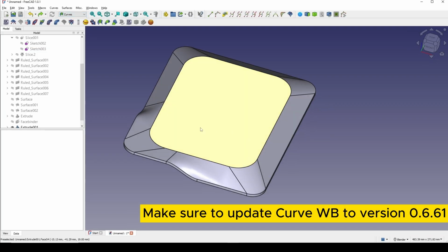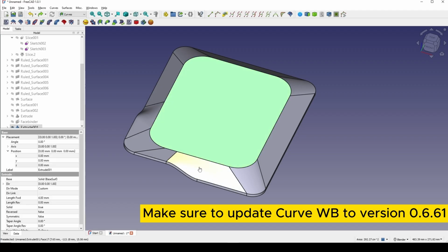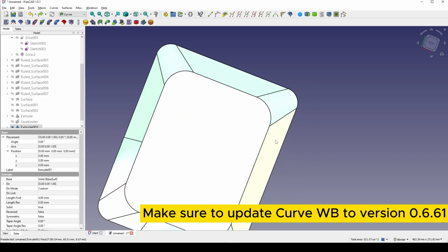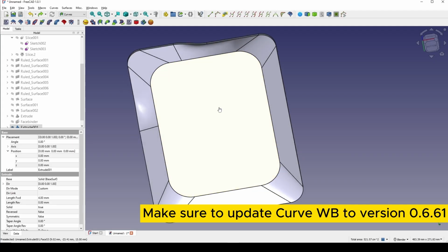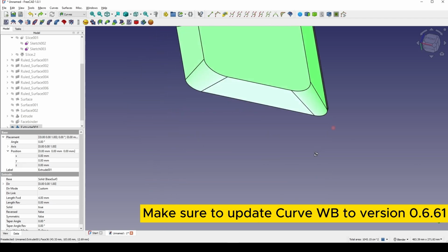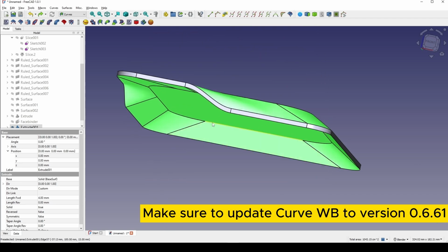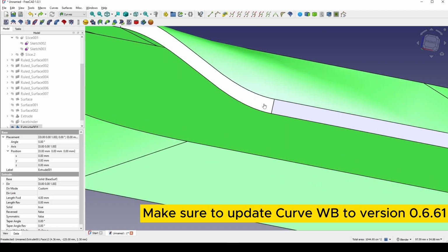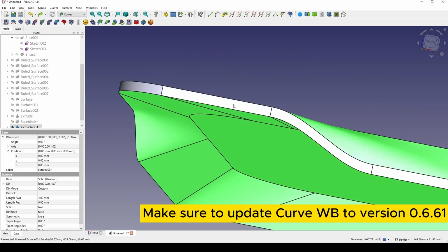And all you need to do is control select faces one by one. Select faces outside one by one. So I will control select all of the faces on top and all of the faces down the bottom. Okay. And all of the faces on the side.